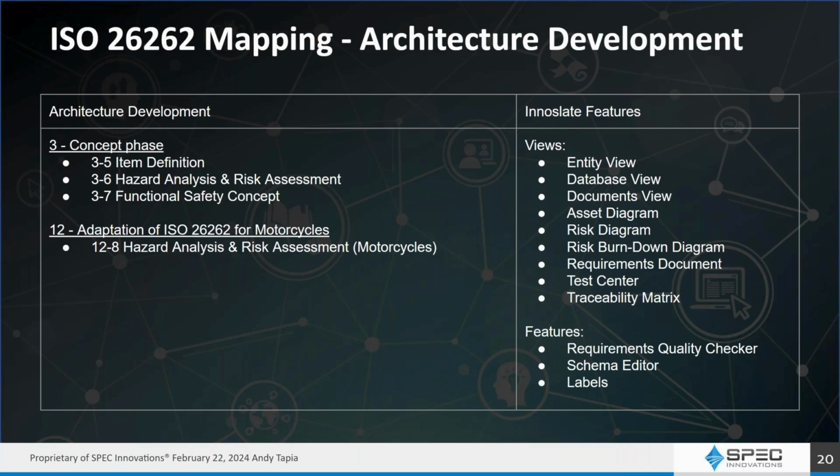And from what I understand, we're making sure to recognize that the system under development is interacting with other components during development, and that we're performing HARA assessments with regards to the severity, exposure, and controllability, and that we're using the functional safety concept to derive functional safety requirements from safety goals.